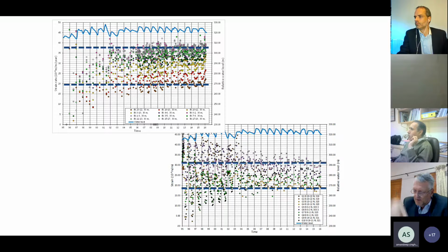And then on that side, they're not constrained. So they can swell more into the gallery. So the one side, they're unconstrained, and then the rest of the side they're constrained. Unfortunately, that is why they actually swell more than what the Carlson strain gauges actually show to you.